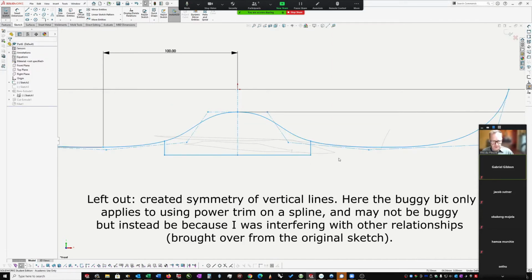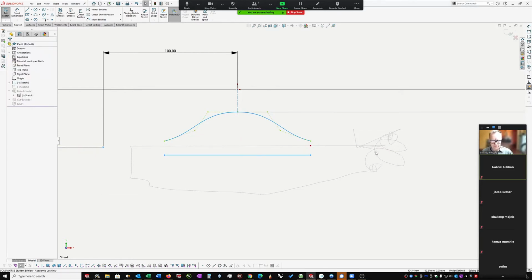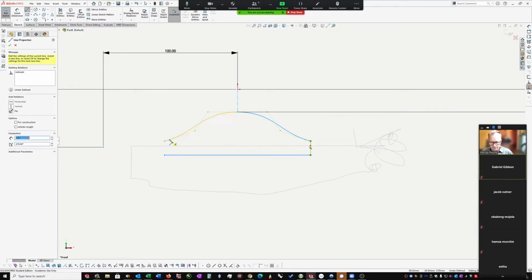Oops. Oh, you gotta watch out when you do this power trim command. It seems to stay active while this dialog box is in place, and then it cuts all sorts of other stuff out for you. You see that? It's still going, and I'm not clicking my mouse, but I'm going to click again, and it's shot right through here. Okay, so a little bit of weird behavior. That's not me, I promise you. That's actually the program.